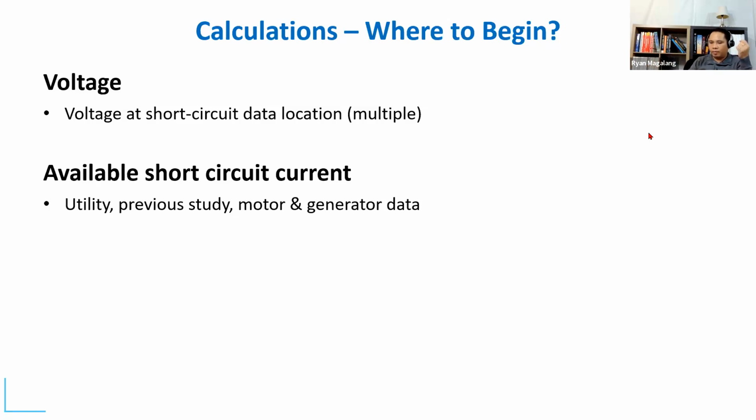So every 5 years, you'll have to do this periodic analysis, and not just for short circuit, but also for arc flash. So I forgot to add that. So arc flash analysis is another thing that we do. So every 5 years, we'll have to do this arc flash study and relabel the devices, your panel boards, your MCC, your switchgear.